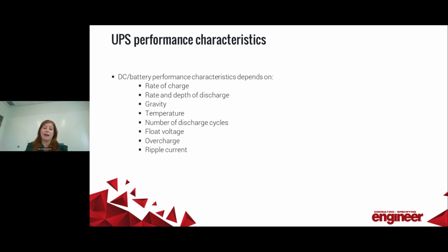The valve regulated have a smaller lifespan of 5 years. They are the lowest cost of all three and lowest maintenance. They still have a ventilation requirement because they do emit hydrogen into the atmosphere, but it's at a much smaller rate than VLA. And they have a very short life, which is the con there.